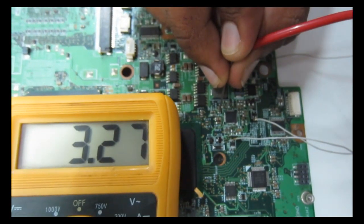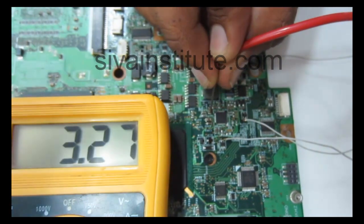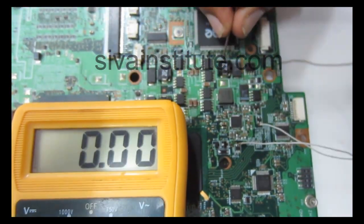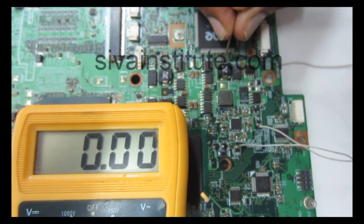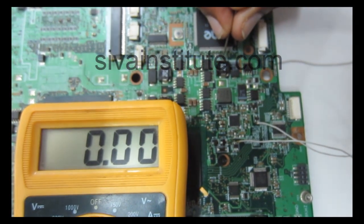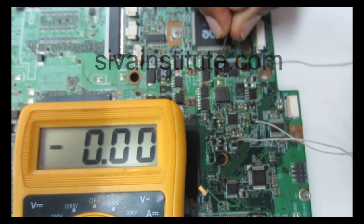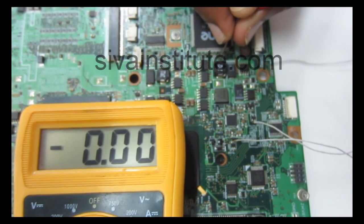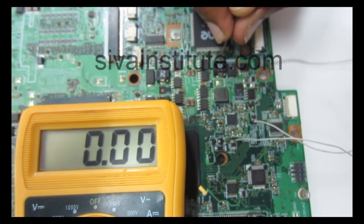You will see here 3.3 volts is okay. 3.3 volts is okay. We will see at the coil. No voltage at this point. After pressing the power button, this voltage will come. Without pressing the power button, this voltage will not be present. When you press the power button, this voltage will come. Bias and SIO chip is okay.